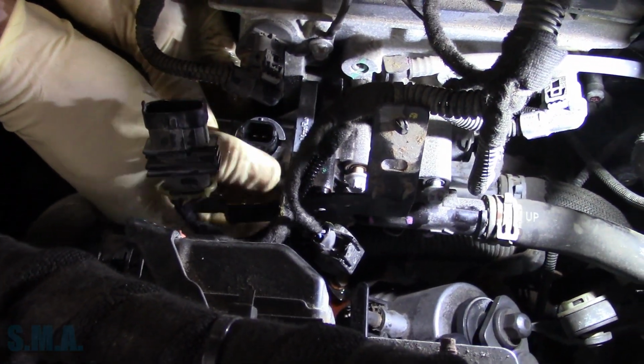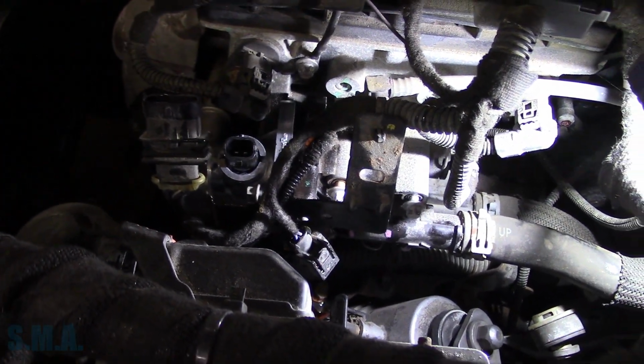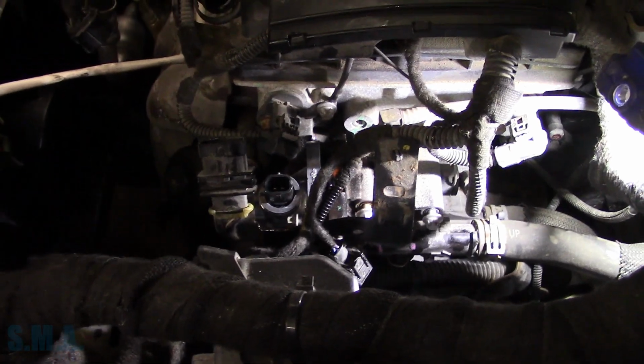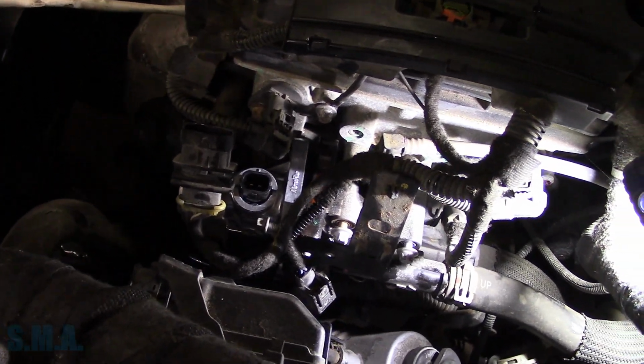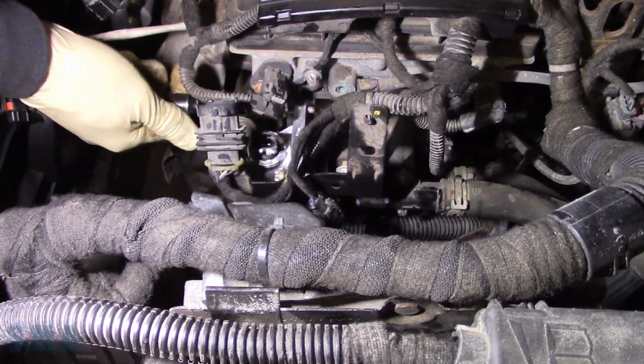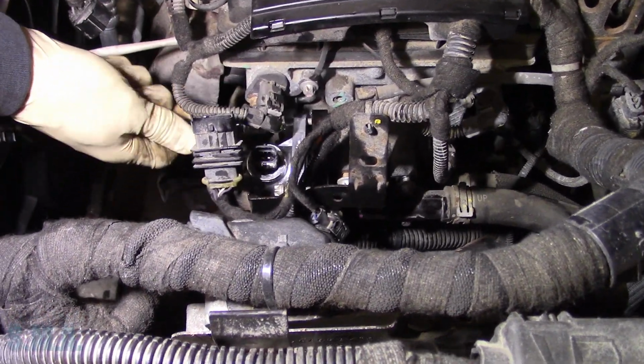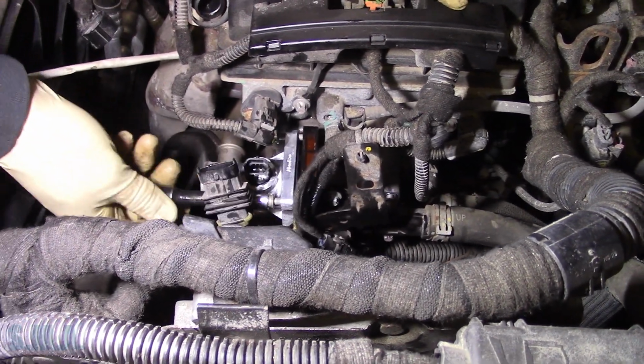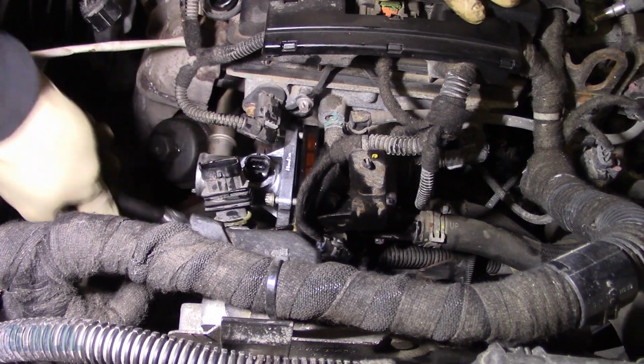Just like so. Alright. I slip the new thermostat in there, we'll put the bolts in that. If I'd known we had to take this off, I would have gotten a new O-ring for it just to be on the safe side. It is an O-ring gasket, so it shouldn't have a problem resealing. Usually good for a couple of tries. Famous last words. So we'll get that torqued on there to factory specs, obviously. Torque the housing back down, kind of get some things put back together here. And the leak should disappear at that point.